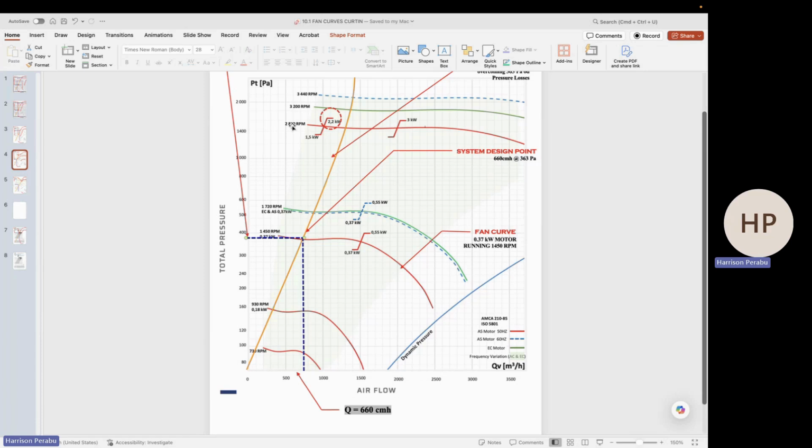So think about it. The next time you install a ventilation system, ensure your system provider puts a lot of emphasis on the fan curve. If it is possible, ask them to give you several fans and choose the best option. Ask about the contingency they put in the process, the type or the RPM, and what is the basis of the selection. So this should be one of the most important criteria as the basis of the overall design.